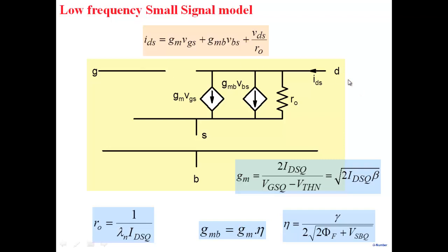Here, note that this is not such a strong nonlinearity. If it is in subthreshold, then we are in the same situation. But if it is in saturation, that's where most of the analog circuits work. MOS-based analog circuits most of the time are in saturation region.